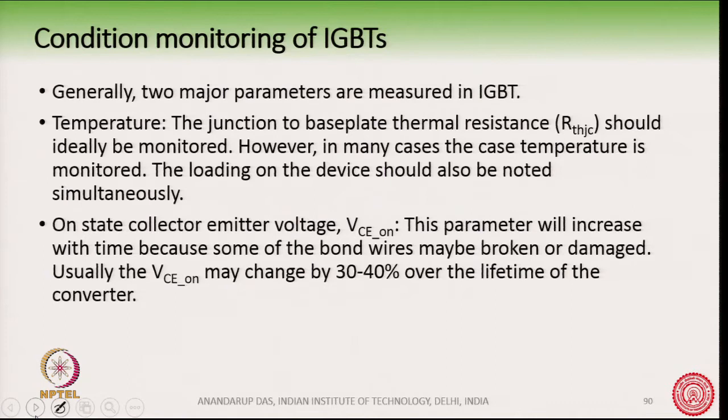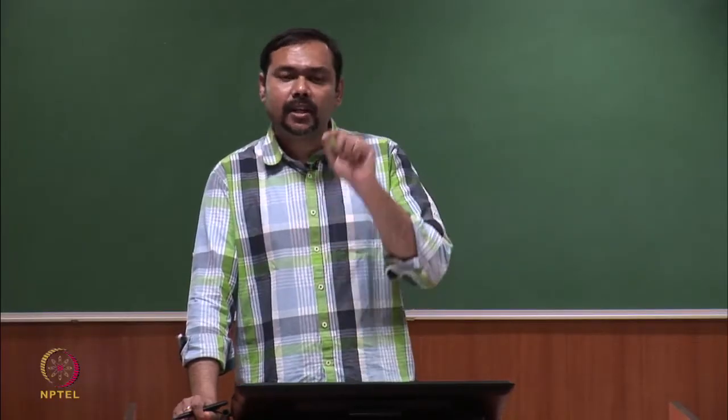So, ideally we should monitor the junction to base plate thermal resistance, or the temperature there. But in many cases access to that point is very difficult. Sometimes the manufacturers give a temperature sensor right at that point and that terminal is available.